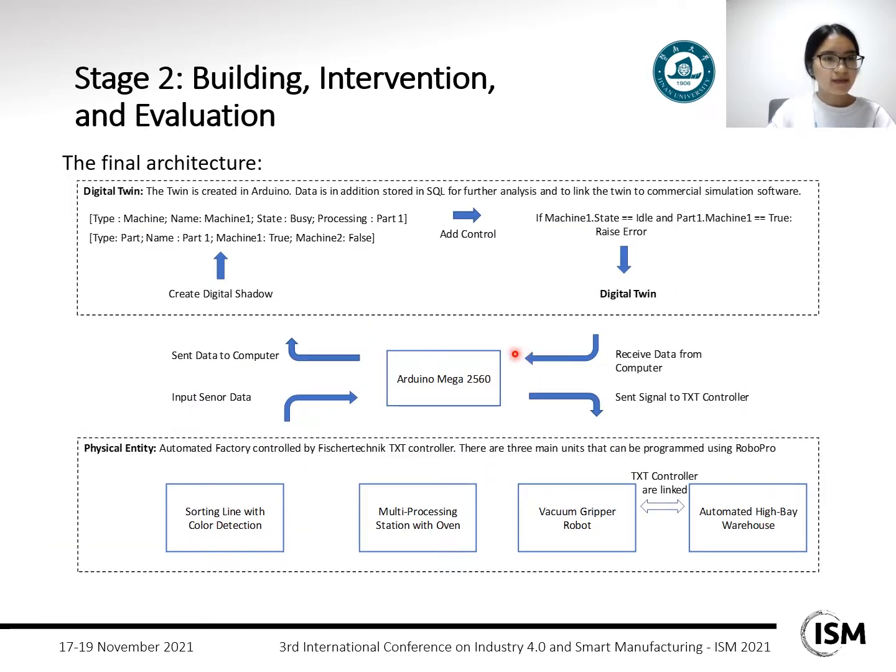According to the answers to the questions above, we design a solution of building a centralized digital twin of production logistics. There are 3 layers in this architecture, including the physical layer, the communication layer, and the virtual spaces. All the sensor data is transmitted to the virtual spaces through the PLC, and using this data, we can build a digital shadow of the physical object.